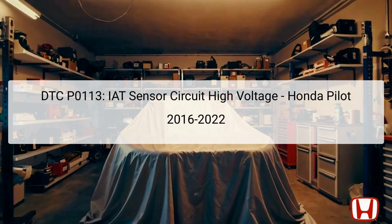A malfunctioning IAT sensor can lead to performance issues, as the ECM may not compensate correctly for the air density and temperature, affecting fuel mixture and overall engine efficiency. Understanding this DTC is essential for technicians troubleshooting a Honda Pilot from 2016 to 2022, as it ensures that the vehicle operates at its optimal performance. Correctly diagnosing this code will enable you to focus on maintaining or replacing the faulty component to restore functionality.